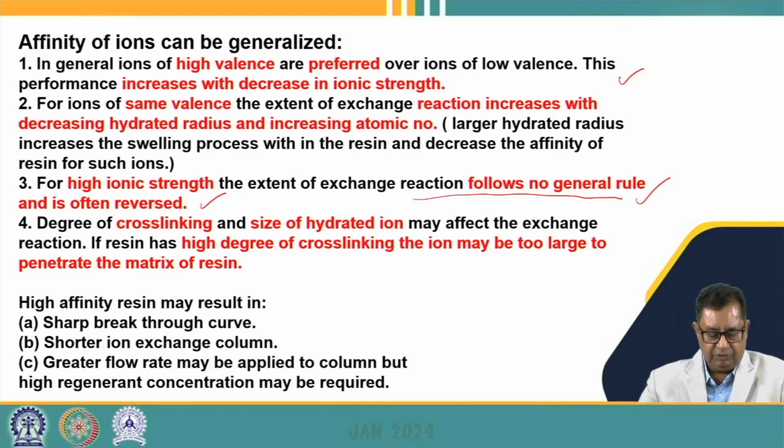Similarly, the degree of cross-linking and the size of the hydrated ions may also affect the exchange reactions. For example, if we have a high degree of cross-linking, the ions may be too large to penetrate the matrix of the resin, and the efficiency of the ion exchange may decrease because of the lesser space available for the ions to penetrate and go inside the resin.